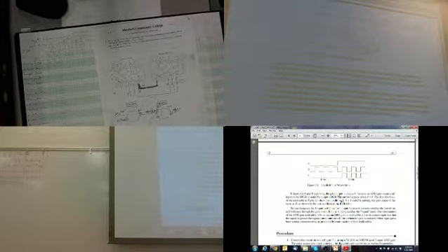So now you can see this yellow signal. Now these are color coded, of course. This yellow signal goes to this yellow button, which goes to that yellow waveform. So it's really easy to use. Now you can see that if you change the frequency over here, and you change the frequency on the scope, then you know that it's working. If I put this switch, same thing happens. They're following each other. Now when you turn this on, the first thing I do is turn this oscilloscope on because it takes about 3 minutes to boot up.